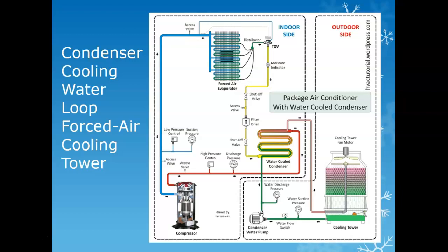This is not freon here. It can be water or it could be some other fluid. Generally it's water because water's cheap. What they're doing is they're forcing water over the coils. As it forces it over the coils, the water sucks away the heat from the other side of the coils. And then once it makes it back to that water tower, it releases that heat and the cool water falls to the bottom and gets sucked back into the system.